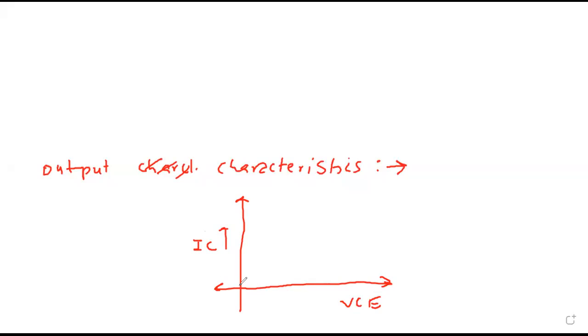Now, as you increase this voltage, the collector current starts increasing and finally gets saturated. Suppose I keep at that time base current 5 microamp. If base current is increased, that means you have increased base emitter voltage. So actually pulling force increases. More electrons are pulled at same voltage. So we get this graph slightly shifted upwards. This is suppose base current 10 microamp.